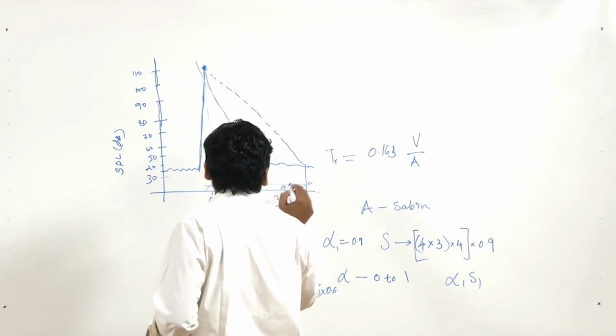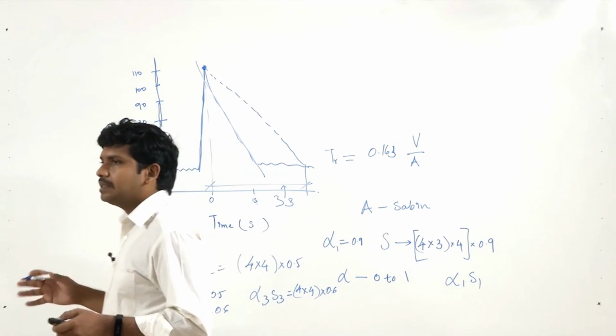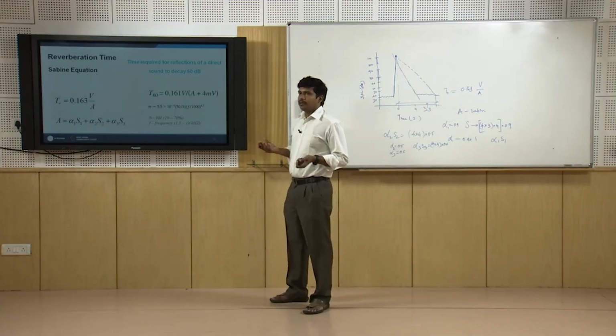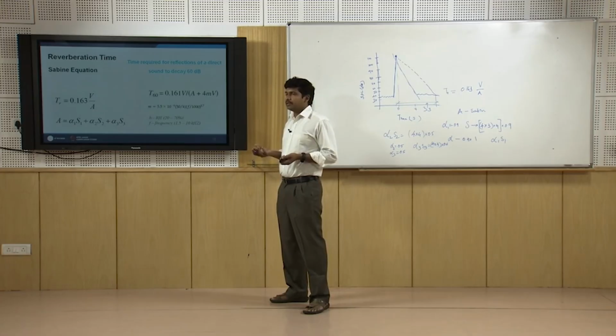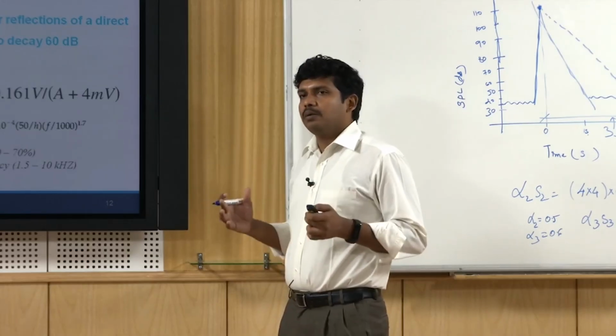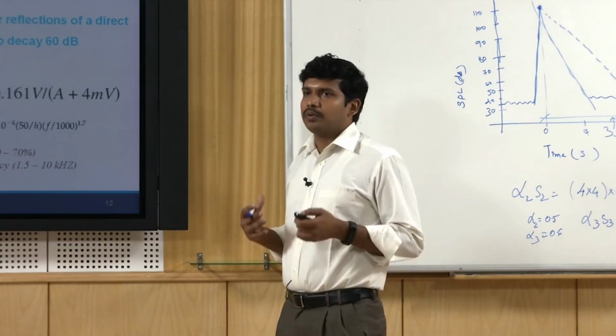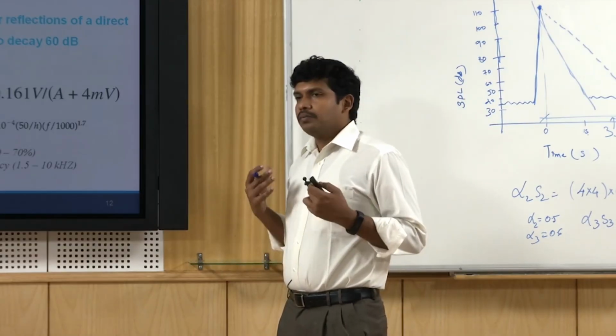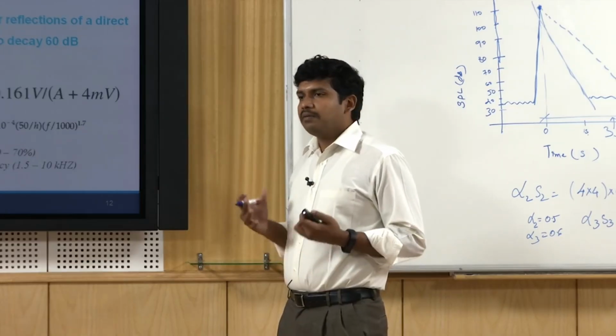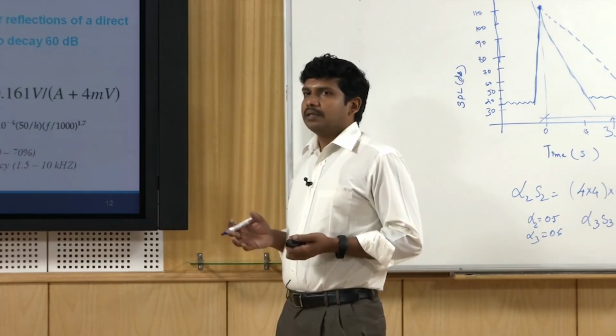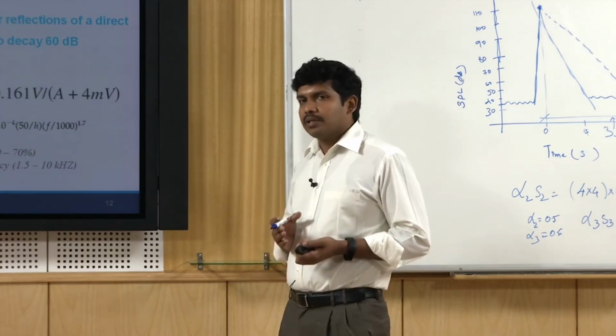If it is taking 3 seconds, then the reflections stay in that room. Imagine you are entering into your new house, you do not have any furnishing, you do not have people staying, nothing is there, just an empty room. If you clap or if you try and sing, if you talk, you will be hearing a lot of reflections. There will be an ambient sound which is continuing, which is not decaying out with closed window. But then eventually you start occupying, you put in your furniture, you have your open windows, people around, everything is absorbing or scattering the sound, then the reverberation eventually comes down.